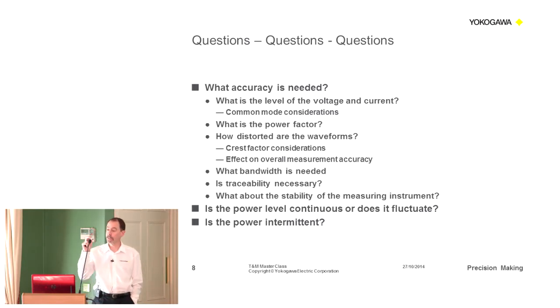Standard oscilloscopes are single-ended, of course. They are ground referenced, except for instruments like our scope recorder, which have isolated inputs. Because you've got floating voltages, particularly on three-phase supplies, you have common mode issues, where common mode voltages will affect the accuracy you're measuring. So that's also something potentially you have to think about.